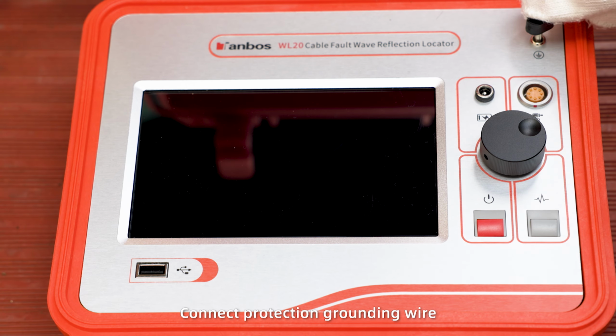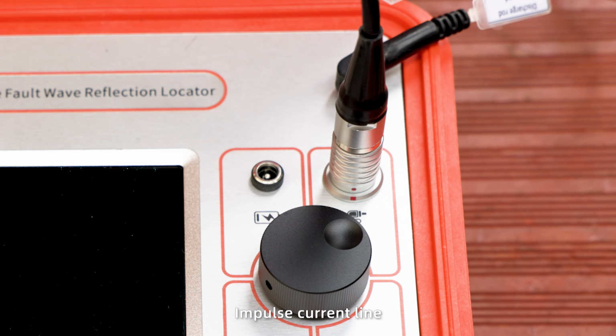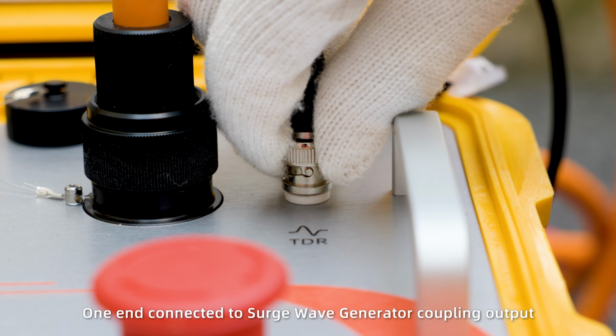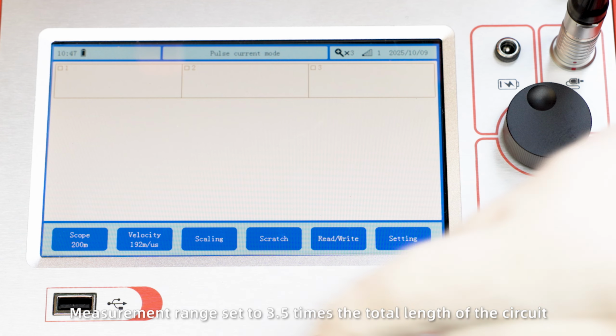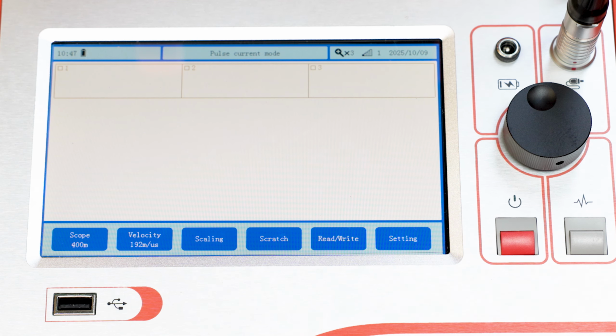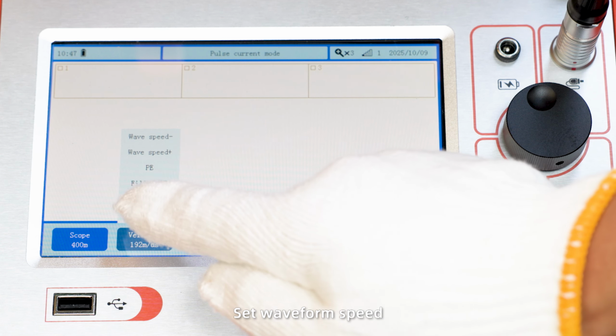Connect the protection grounding wire. Impulse current line: one end plugged into the WL20 host signal port, the other end connected to the surge wave generator coupling output. Set the measurement range to 3.5 times the total length of the circuit. Set the wave velocity.